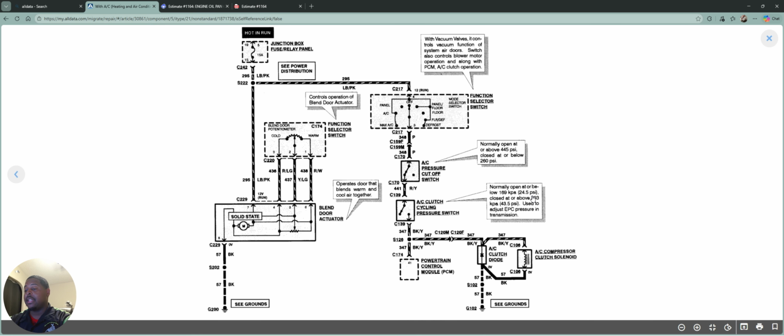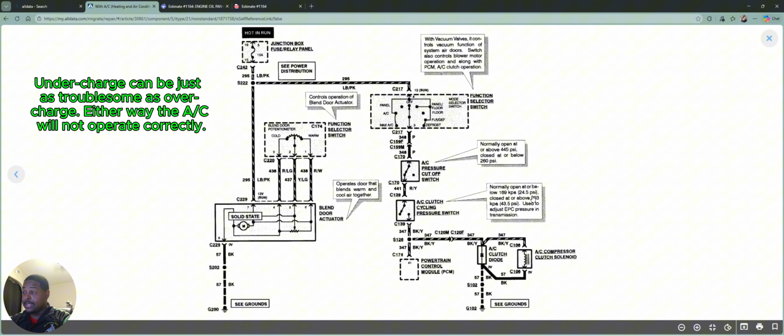And if for whatever reason the charge pressure drops, it will repressurize the cylinder and continue to push refrigerant in. When you're doing it manifold gauge style, if you don't have the cylinder sitting on a scale, you don't actually know how much refrigerant is going in. Like I said, it's possible, but it is definitely not the best way to get it done. And if you're having issues with your AC, that is going to be a variable.